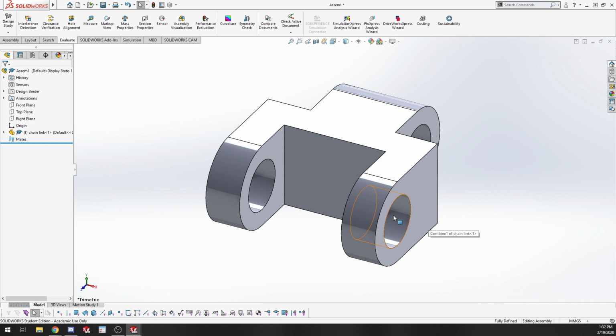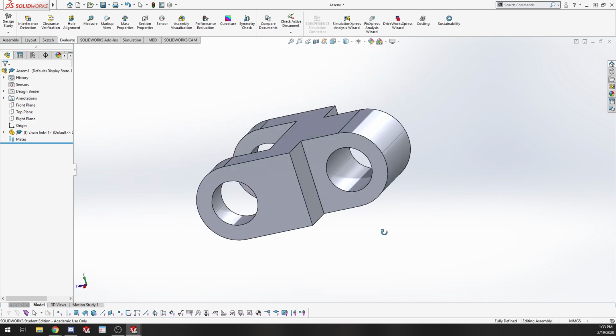When we're building our full car assembly, for example, we'll want to put the frame in first, have that be the fixed thing that everything bolts up to, and then go from there. You don't want to just put in a wheel first and then try to orient your chassis around it. It makes it kind of whack.